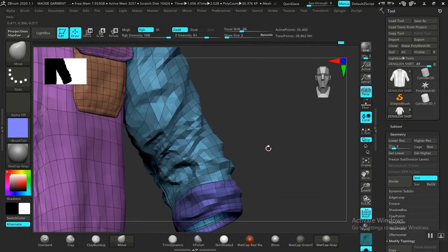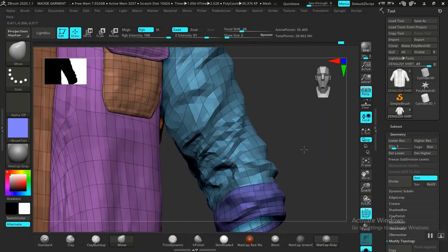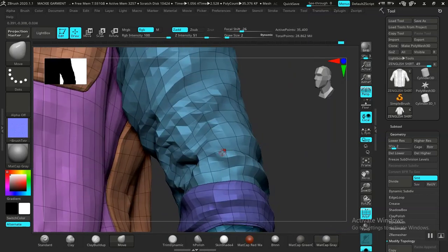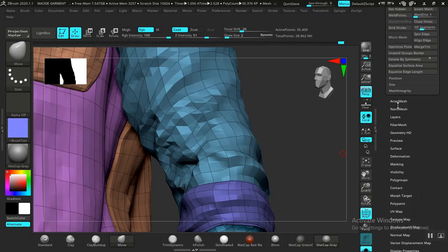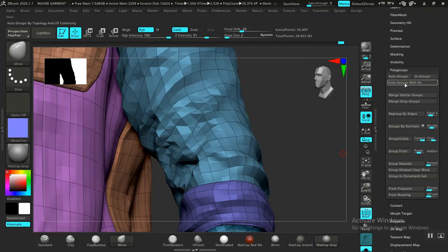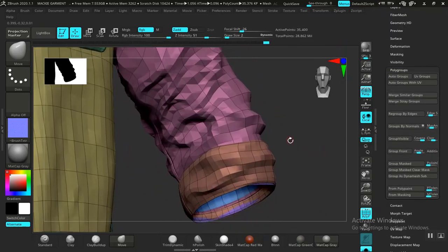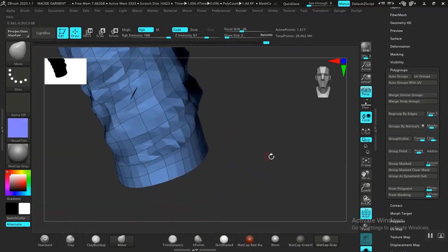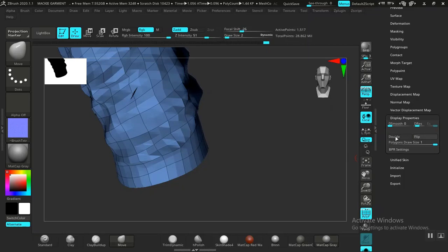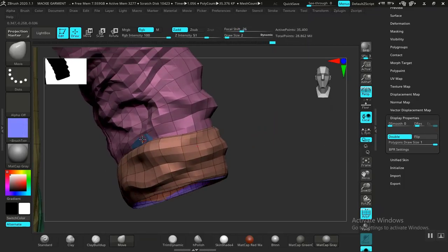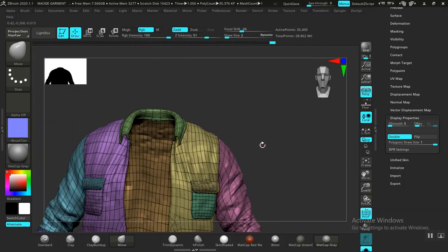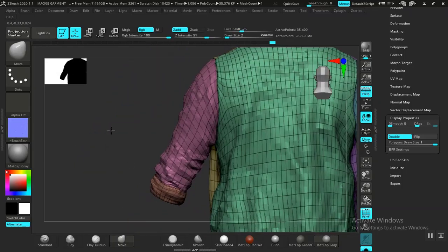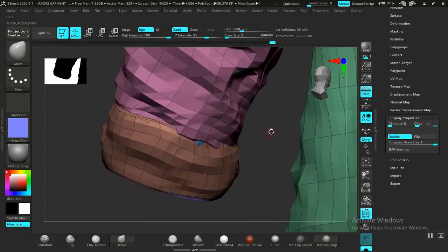Or maybe just export this out at this 35k. Let me just be on the safe side. Let me do auto group UVs. So I'll do auto group with UVs. I think that should reveal the part that has issue. Or more like the inner part like so. Let me make sure double sided is turned on. So now you can clearly see it with double side turned on. You can clearly see it penetrating out. You need to push it back inside. So it's basically a very minor fix. You can see them around here. You can see another one in here also.